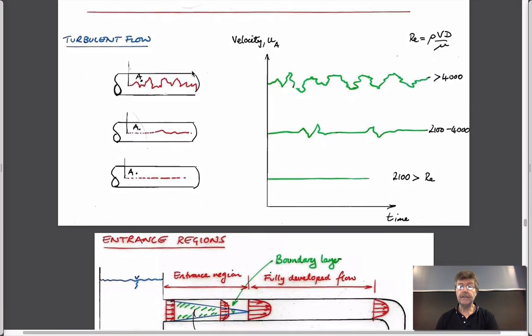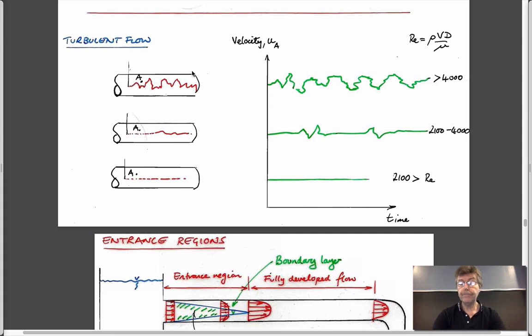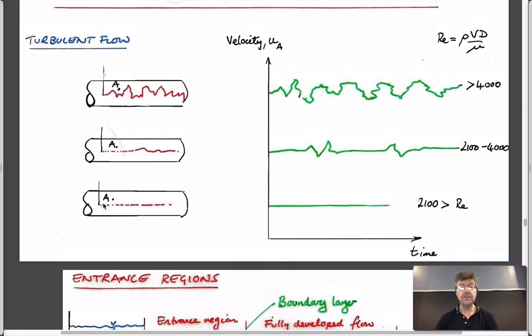When we looked at the YouTube video of pipe flow, what we saw initially at low velocities was this nice dye profile, which then began to waver. As we increased the velocity, we didn't really see it get to this. So when we're talking about the behaviors of these systems, there are two things that are important here. One is that the roughness of this wall is what controls this transition, we'll find, to turbulent flow. We've called this relative roughness epsilon, and there's a diameter that's attached to this pipe.